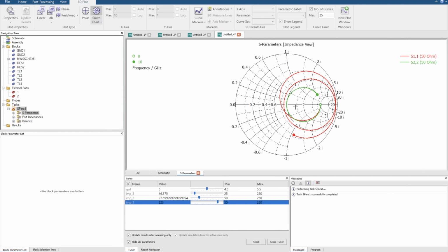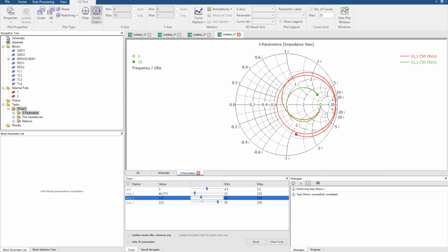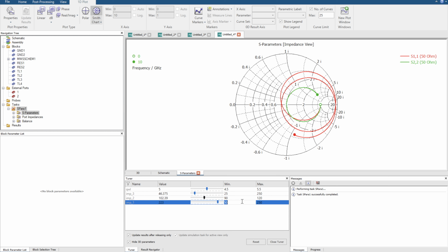So we're getting there. So remember how it pulled it down using the impedance of the middle element. Well, now we can pull it, oh, very sensitive. So let's go for the min value of 90 and maybe the max value of 120. So we have some more resolution to work with. And then maybe 200 as our min value for the impedance of the first element. So I'm going to drive it a little higher. I'm trying to get that little crossover point, and I'm just going to tune forward, sorry. So I'm overestimating, and I'm trying to drive it. Nearly there. Can I get it?